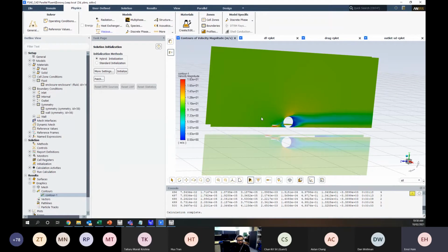Multi-phase mixing, K epsilon, I think K omega is just as good for it. So K omega is K epsilon in the bulk flow field. It just has the shear stress transport model near the walls. Once again, these are questions between the two. I can't answer them. It takes research. Your research group will have a preferred model based on previous work done, things like that. So it's a question that's unable to be answered on the spot like this.